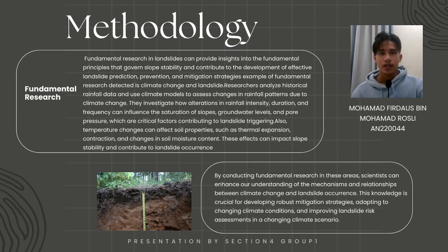Researchers analyze historical rainfall data and use climate models to assess changes in rainfall patterns due to climate change. They investigate how alterations in rainfall intensity, duration, and frequency can influence the saturation of slopes, groundwater levels, and pore pressure, which are critical factors contributing to landslide triggering.